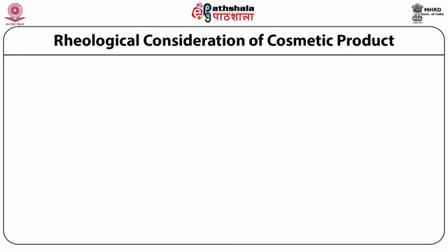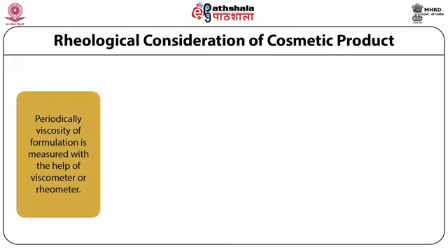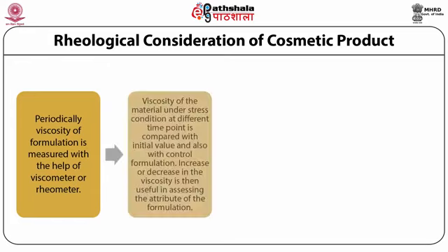Rheological consideration of cosmetic products. Periodically, the viscosity of the formulation is measured with the help of a viscometer or rheometer, and the viscosity of the material under stress conditions and at different time points is compared with the initial value and also with the control formulation. Increase or decrease in the viscosity is then useful in assessing the attributes of the formulation.